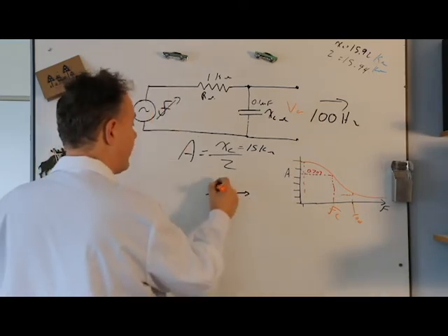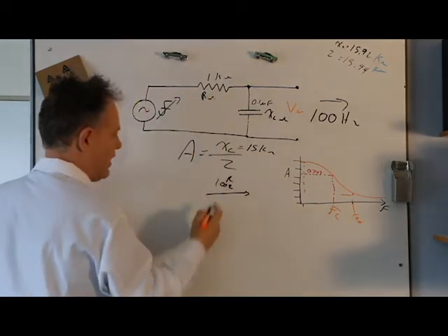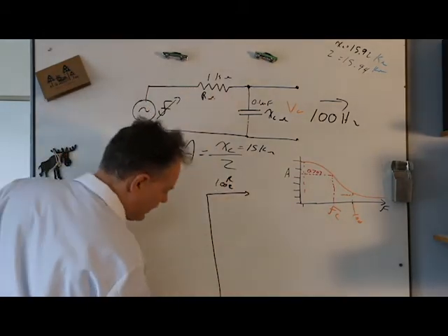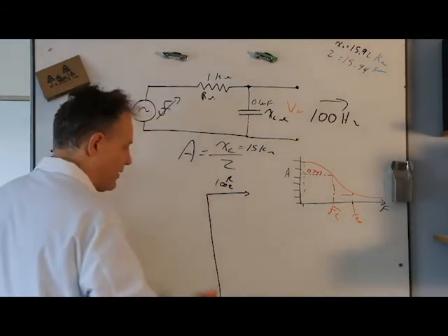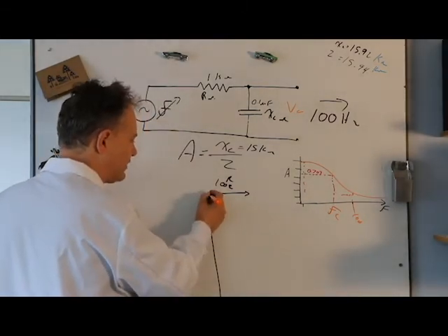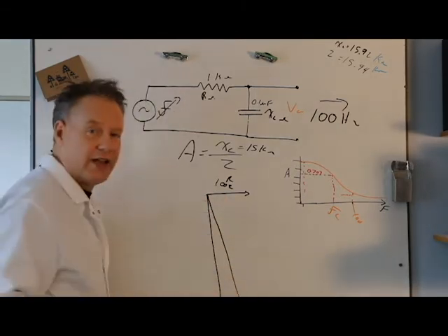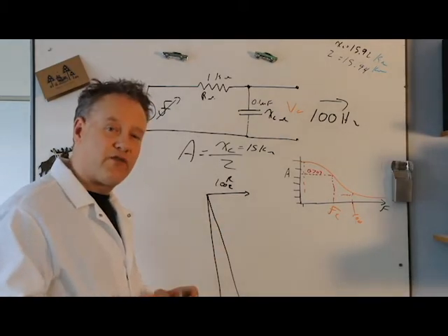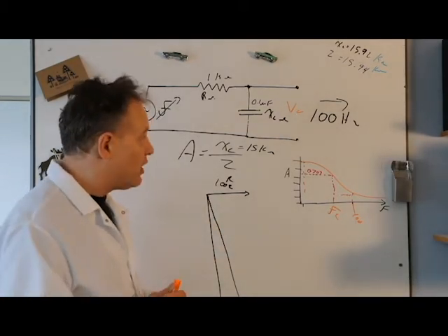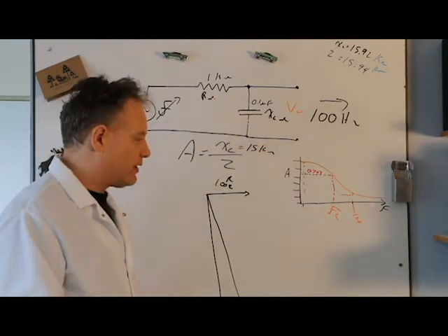If that is 1,000 ohms, which is R, right? This is going to be way down here, like way down there. So our impedance triangle is actually going to look like this. Our Z is going to, this angle is going to be really huge. And that's kind of what we want for a low pass filter, because we want this guy to be much bigger than that guy. So that's the impedance triangle for this.